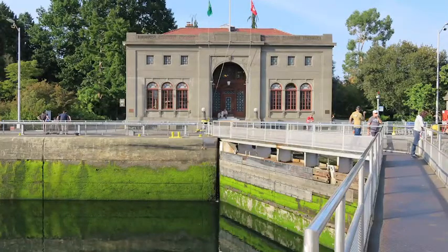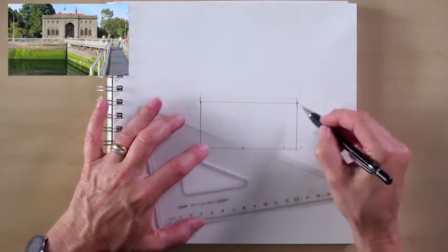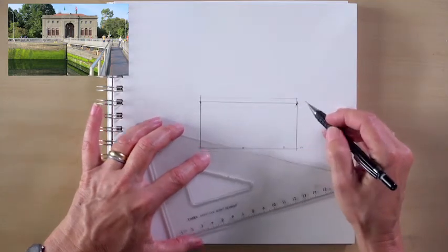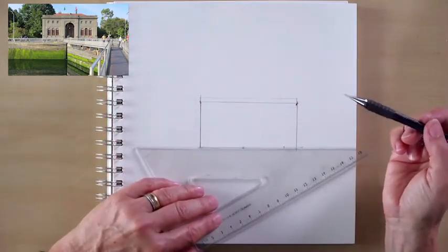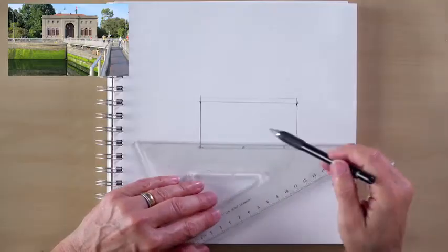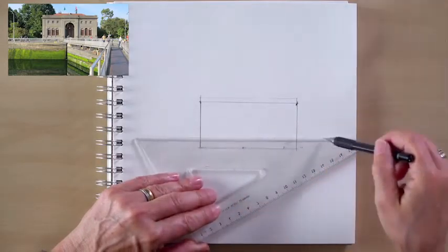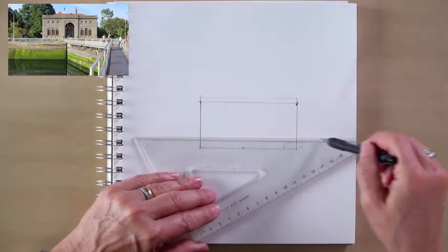The next thing I'll do is try and find my vanishing point and eye level line. So when I'm drawing an elevation view like this, there's not a lot of receding lines to choose from on the building because it's really just the face of the building. But I can look for little places like this and a little overhang here. There's a little perspective there. Another real clue is the height of the heads of the people, because when I'm standing there and if the ground is level, all the eyes kind of line up. So that would put the eye level line somewhere right about in here.